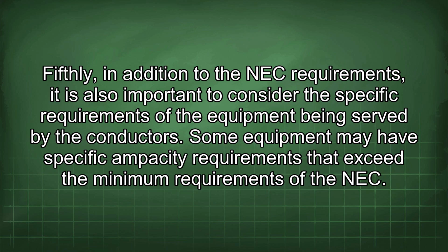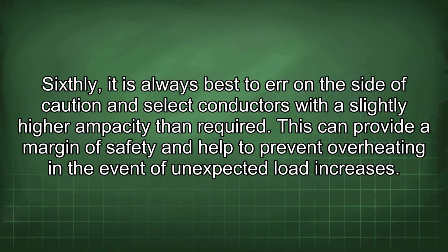Fifthly, in addition to the NEC requirements, it is also important to consider the specific requirements of the equipment being served by the conductors. Some equipment may have specific ampacity requirements that exceed the minimum requirements of the NEC. Sixthly, it is always best to err on the side of caution and select conductors with a slightly higher ampacity than required. This can provide a margin of safety and help to prevent overheating in the event of unexpected load